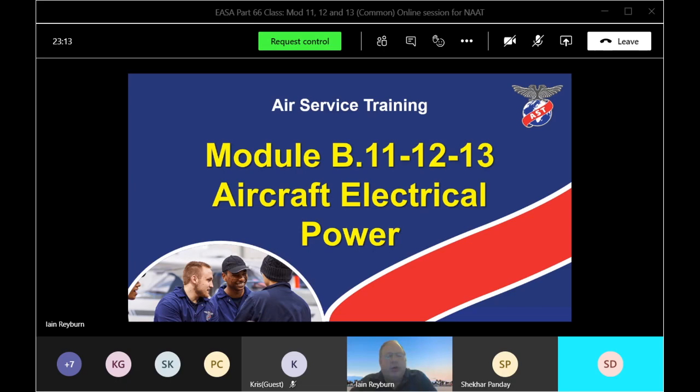Next thing we're going to look at is contactors, power contactors. Okay, there's two types. There's a latched power contactor and a power contactor itself. I just want to highlight a couple of things, gentlemen, because we need to know it before the next thing. Here's my main contacts, okay? So these are the main contacts, and that's going to be like my A phase, B phase, C phase. And these things are what's called the auxiliary contacts.